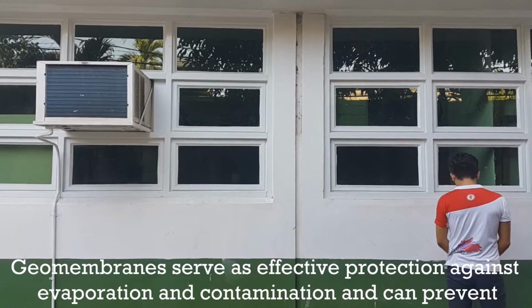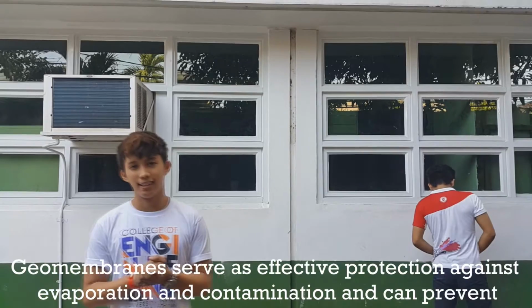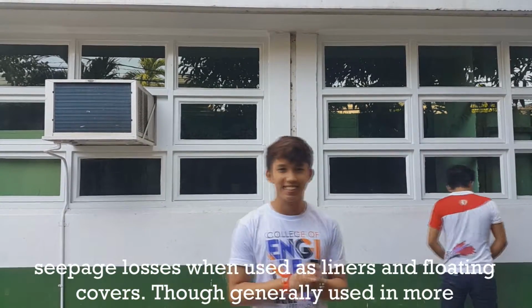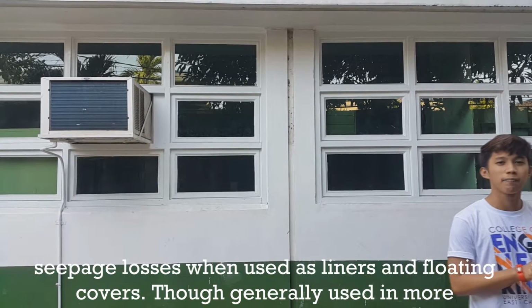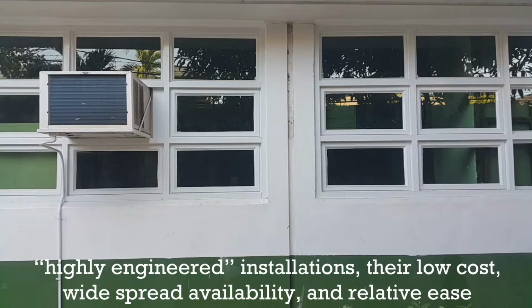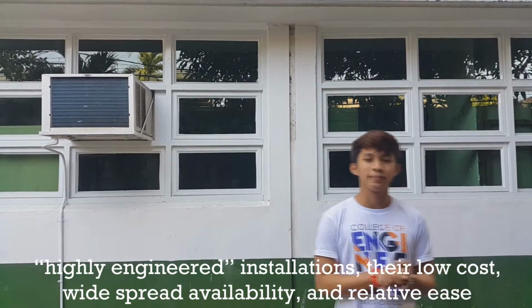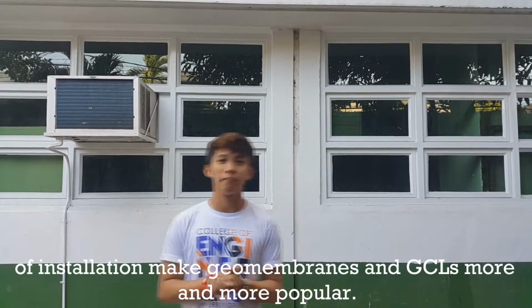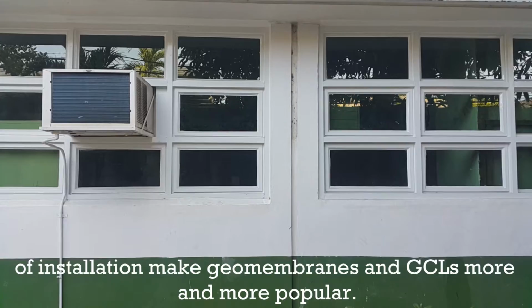Geomembranes serve as effective protection against evaporation and contamination and can prevent seepage losses when used as liners and floating covers. Though generally used in more highly engineered installations, their low cost, widespread availability, and relative ease of installation make geomembranes and GCLs more and more popular.